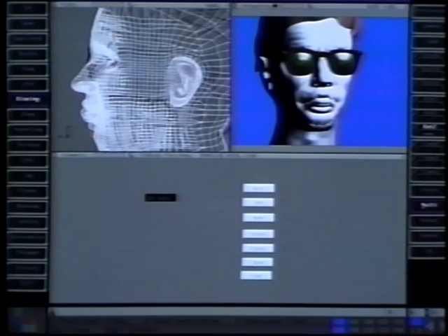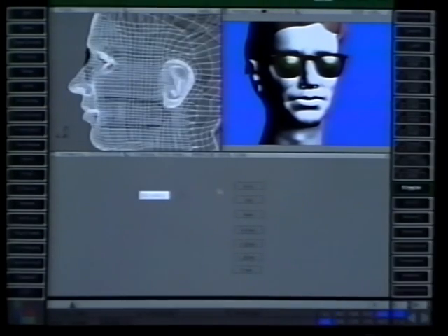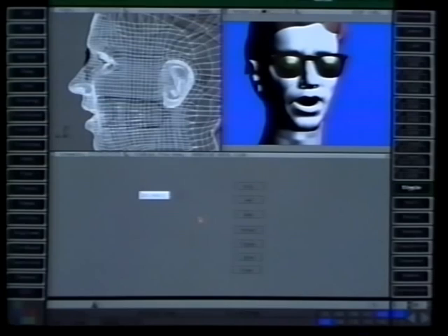This way, the center's location for each model can easily be frozen to the same coordinates, and it's easier to compare models. Then, before beginning your animation, you just go through and can use the schematic window to select key shapes for each of the poses in your library. After they're assigned as shapes in your shape list, you don't need the original model of each pose in the scene anymore. Although, of course, it's a good idea to keep a backup copy of these models somewhere for when you have to reassign them.